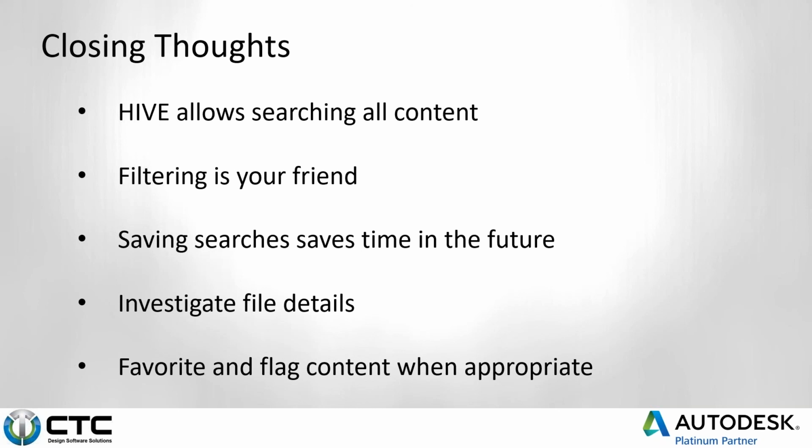For right now, Revit is the only vertical, but you can certainly use things like SketchUp content, Dynamo content, AutoCAD content directly from HIVE as well. Just make an application-specific library, throw the content in there through the Windows app, and then you can certainly go through and drop that content directly into those other design environments as well. And it inserts into them just like it would out of Windows. So you can search and tag SketchUp files, certain collections of content, have your own kind of warehouse and just drag and drop into SketchUp. That does work.